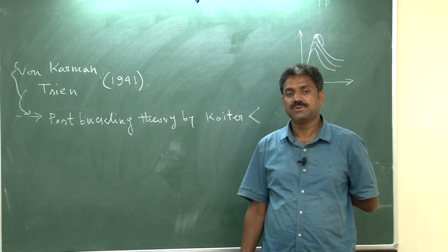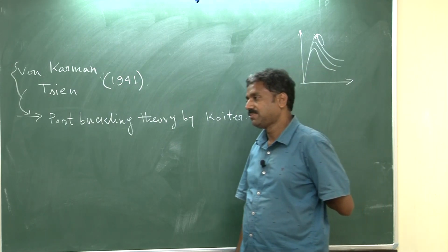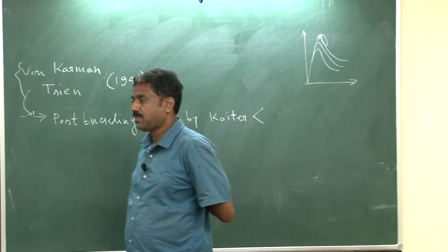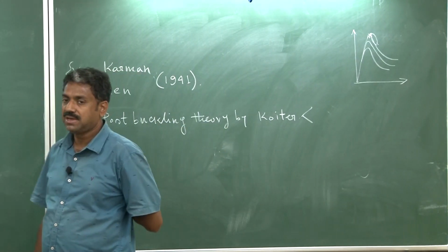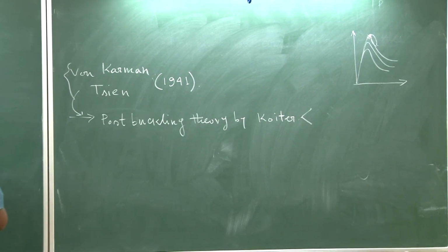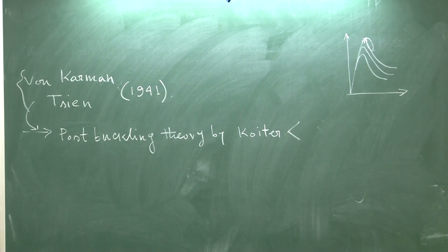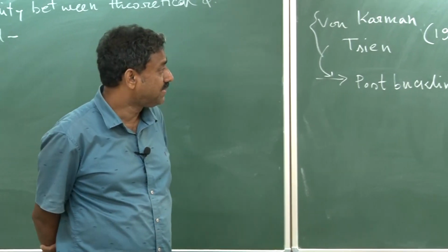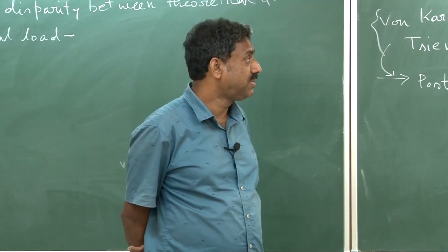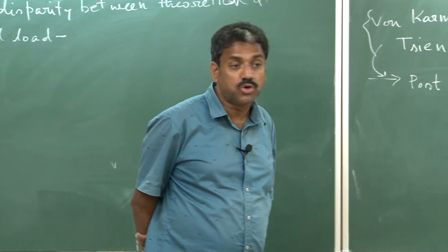That is what the asymptotic theory is. It is some kind of approximate solution to the nonlinear differential equation. It used a perturbation expansion and the asymptotic property of the series. They use an asymptotic series and perturbation of the field variable to solve the equation, and it is an approximate solution that depends on the smallness of some asymptotic parameter. Those things have been given by Koiter's post-critical theory, which explains this load drop, okay.